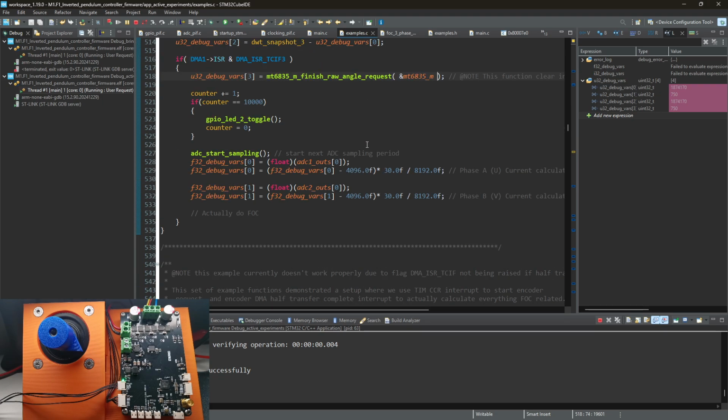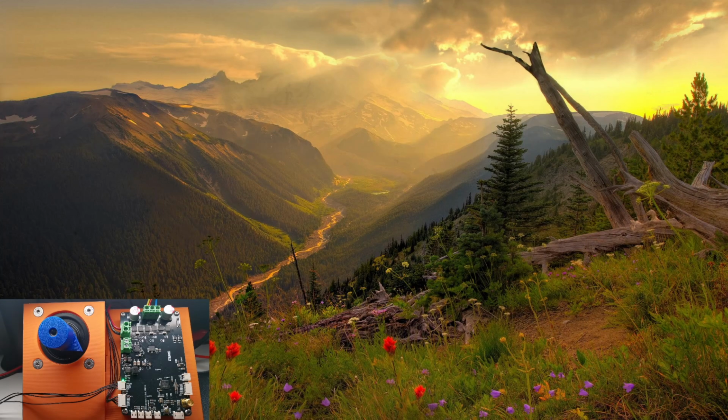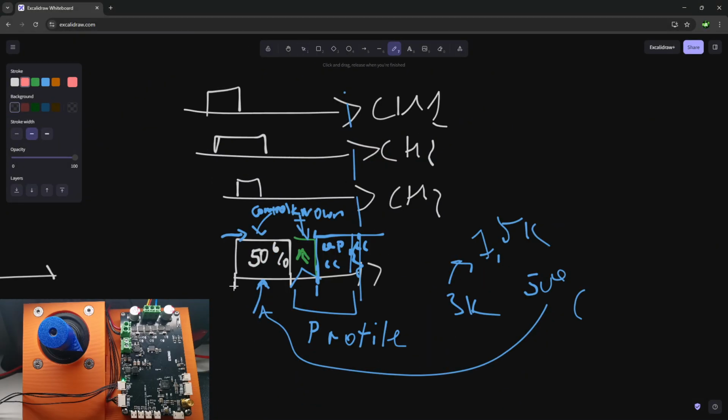I just want to make, for example, testing, because there's a point in time, this point in time. Where is my drawing? That point in time can change depending on your code. When you add a lot of code, for example, you add some logic, you don't control the motor as a simple position or speed control. You, for example, make a balancing robot or something else, and you add 2K additional calculations. You have to make this period smaller.